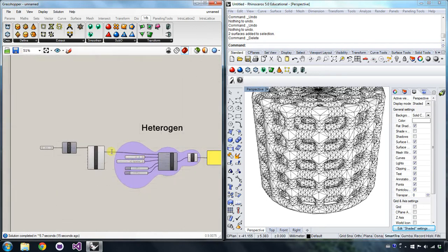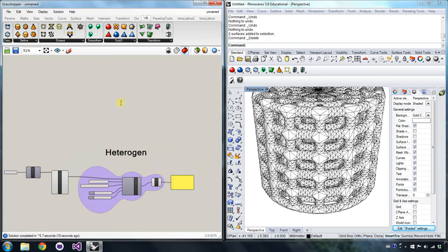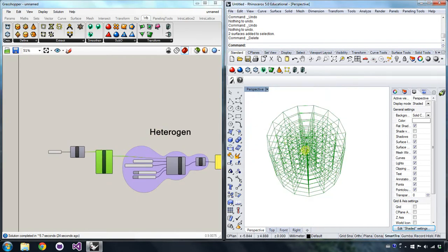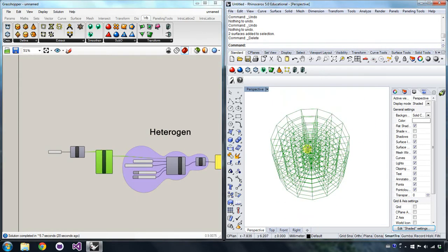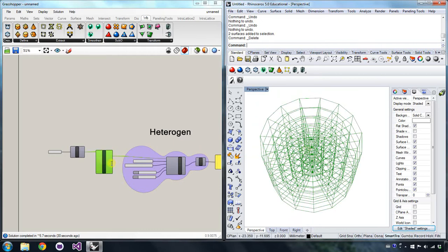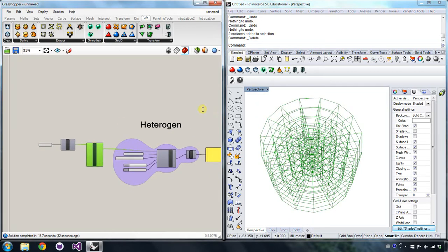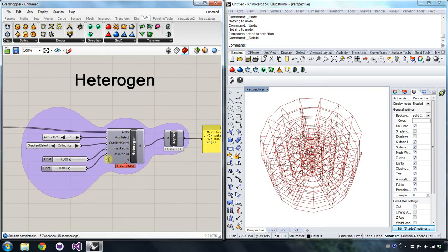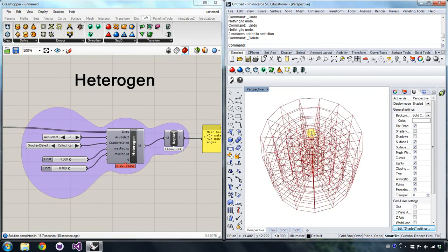Another point is that the FEA optimization comes in at the frame level. So let's say we have this frame here. We'll actually output a beam element model of this frame to an FEA software. We have interfaces for Nastran and HyperWorks, and based on the feedback we get from the FEA software, we'll adjust the radius of the struts at specific locations.